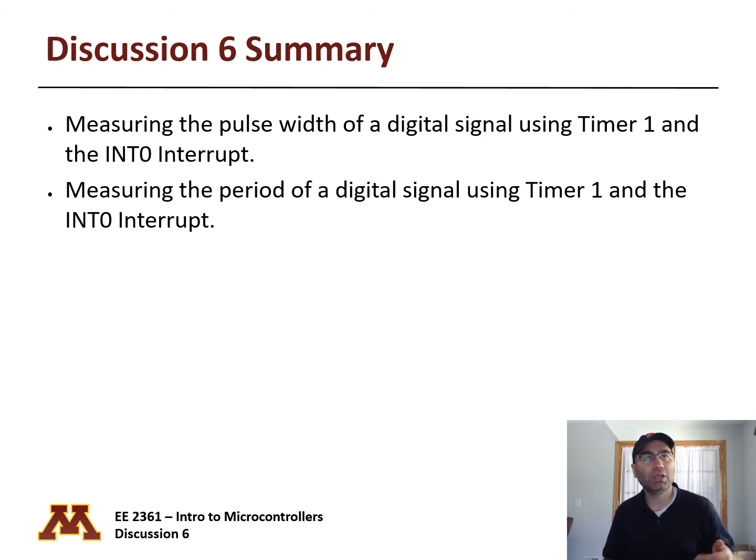So with the INT0 interrupt, you can have an interrupt when a certain pin in your microcontroller changes from high to low or low to high, depending on what you want. So we will use timer 1 and the INT0 interrupt, and we will measure the period of a digital signal again using timer 1 and INT0.